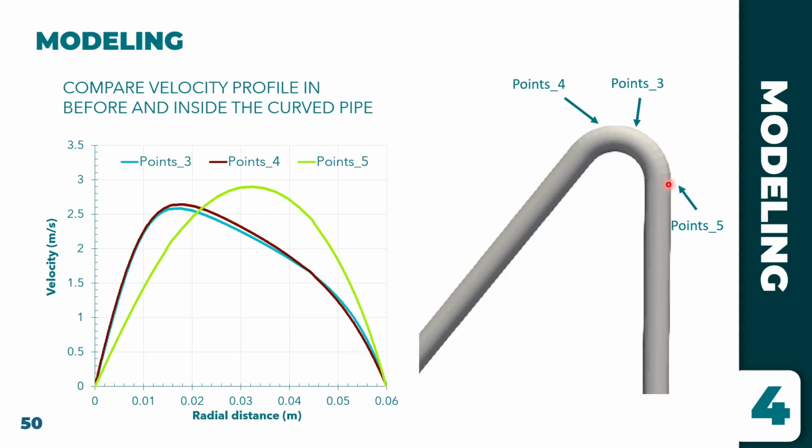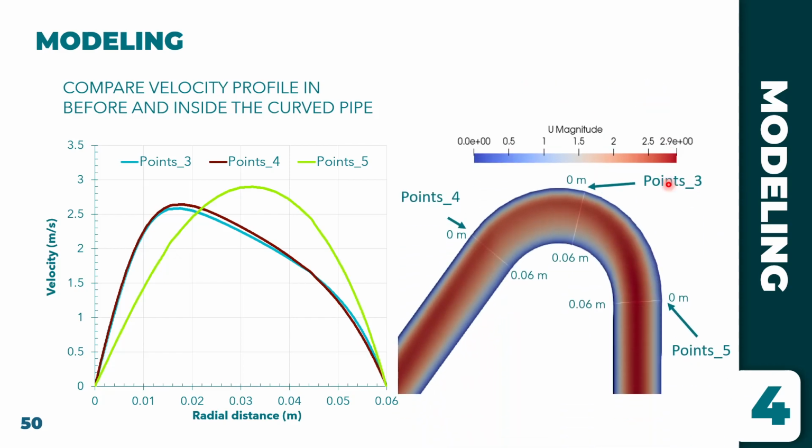And to understand, I have to take a closer look at the velocity profile in here. In the straight part, we see that the fastest area in the velocity profile is in the middle, but in this curved part they have changed their direction, but they cannot do that quickly because of the high momentum in here, so they cannot maintain the fastest area in the middle.